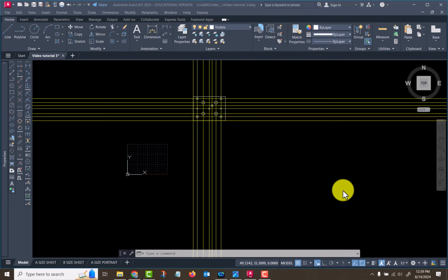In this video we're going to talk about ordinate dimensioning, and you should have read the paragraphs in the textbook about what it is. And we did an exercise, I think in 1101, where we did ordinate dimensioning, and I went through one way of doing it with offset construction lines to line up your numerals and your text. We're going to go back over it here using the ordinate command and a slightly different method of doing it.